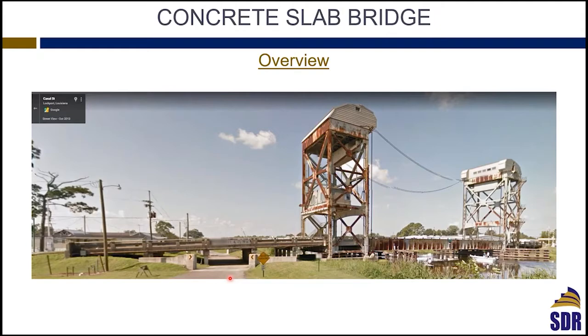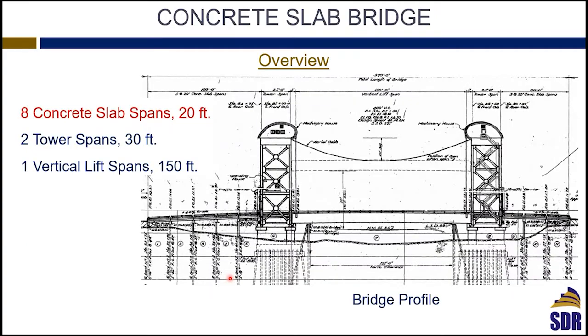Load rating the bridge using the conventional analysis and the conventional load rating techniques, they were getting a load rating factor below 1. Accordingly, the bridge has to be posted. This was an important bridge, and it's crossing over a big canal, and now you are actually hurting the area on the other side of the bridge. So we have to go and do the load testing to determine what's the actual strength of that bridge and to see if we have to keep it load posted or not.